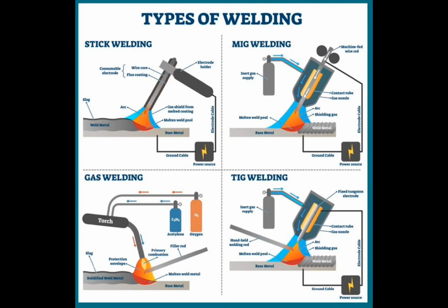Name some types of welding. Oxyacetylene, gas shielded, bronzing, arc, plasma. What is an advantage of electric arc welding over gas welding? Less buckling and warping of the welded material.